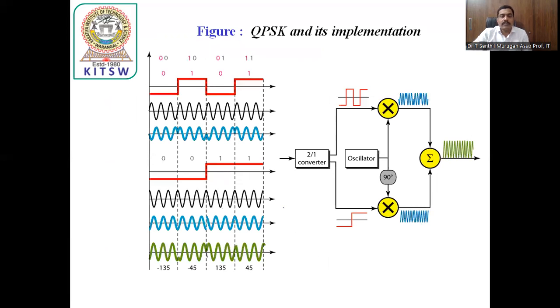So how can we do it? You see here, initially the data is 0, 1, 0, 1. For that it is represented with digital line coding techniques. We are sending the carrier frequency, so accordingly it will be there based on the phase. Wherever the values came, the phase will be changed. This is the modulated signal. But another data we are sending is 0, 0, 1, 1. For that also we are using line coding techniques. Wherever 0 is there, it will send the same value. But wherever 1 is there, it is changing by shift keying.